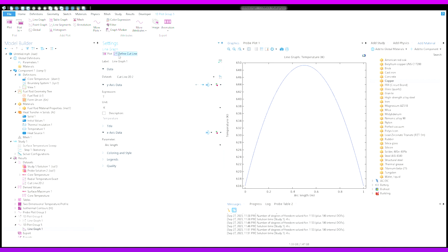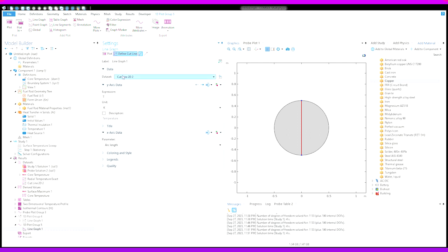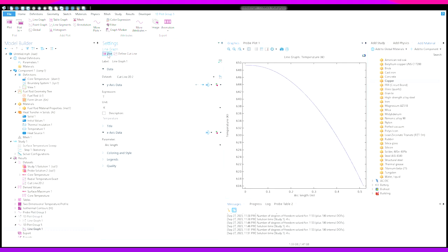So one way you could achieve that is by moving these vertices. Based on which one of these you click, you'll move a different vertex. I have this one clicked, which means this one will move. So I simply put it roughly in the center, left click, and now I plot. And now I have a decent approximation, and this is probably good enough for a lot of applications. However, of course, it's best to be precise.